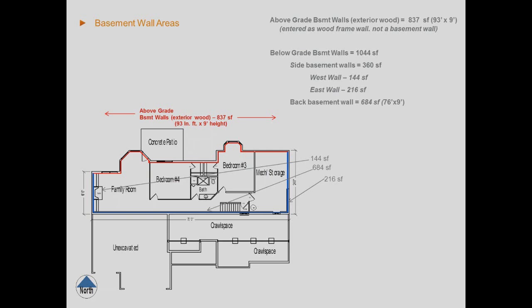They're like components, so take the total square footage and show just one basement wall if they're both the same grade. Enter it up, and then enter the height of the basement wall, depth below grade, and then depth of the insulation, as long as I'm insulating both those side walls to the same depth. And if it's full height insulation, then you're good to go. Show it at full height.